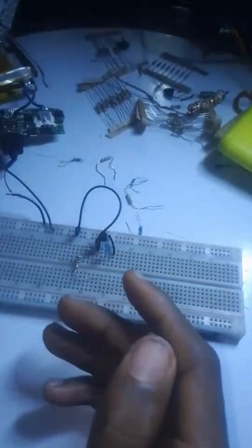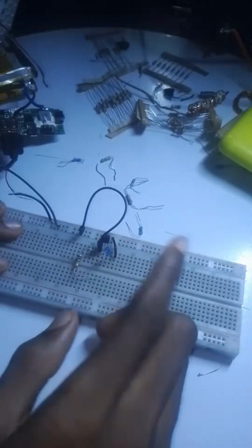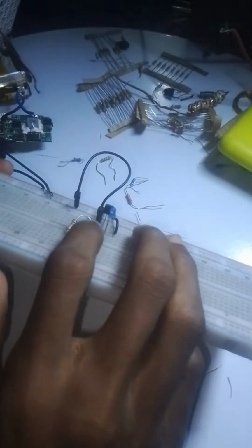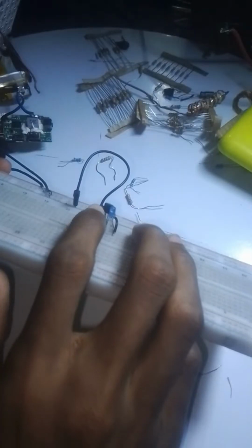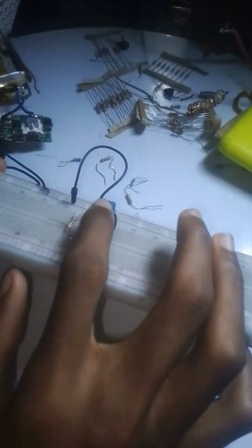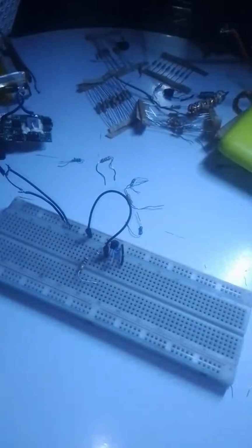So when the transistor is being turned on, it then allows current to flow, thereby completing the circuit and turning on the LED. The LED negative is actually connected to the collector side of the transistor, and the emitter side of the transistor is connected to negative. So when the switch closes, it connects this negative to the bulb's negative, from the emitter to the collector. It's kind of like a switch. When the base has a current flow, the switch closes, and boom, the circuit is complete, and we have the LED light up.